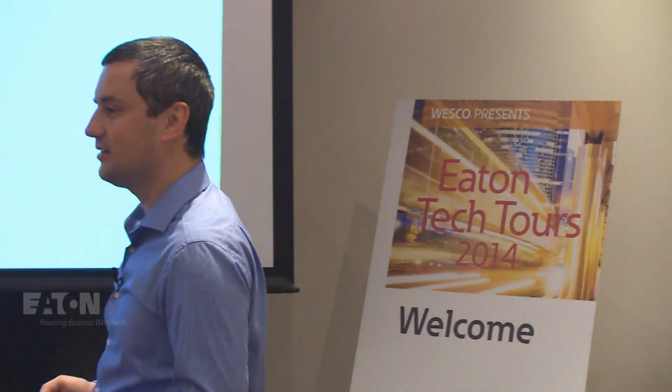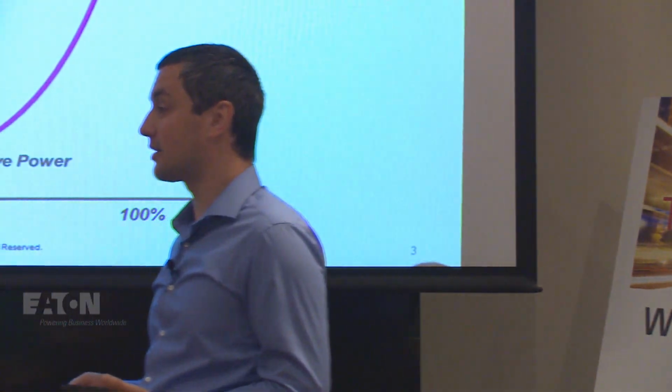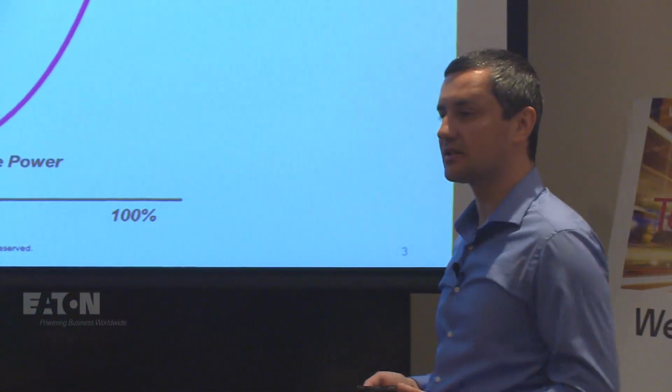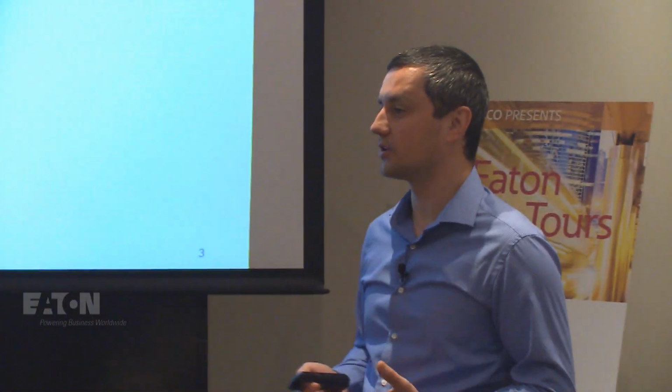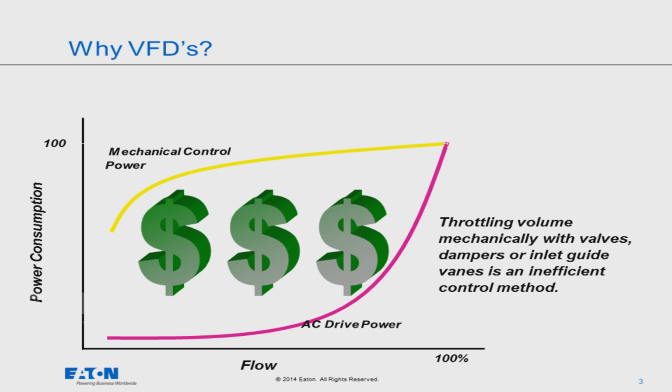Now, if we're using a VFD instead of that, we can actually control the flow by controlling the speed of the motor. So we don't have to run the motor at full speed all the time. So it's all about saving dollars, okay?